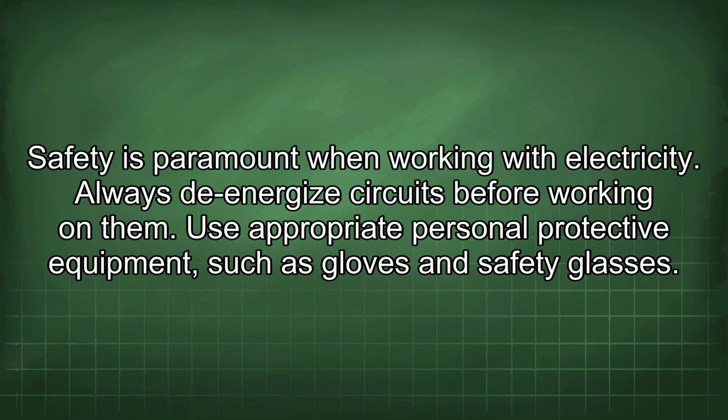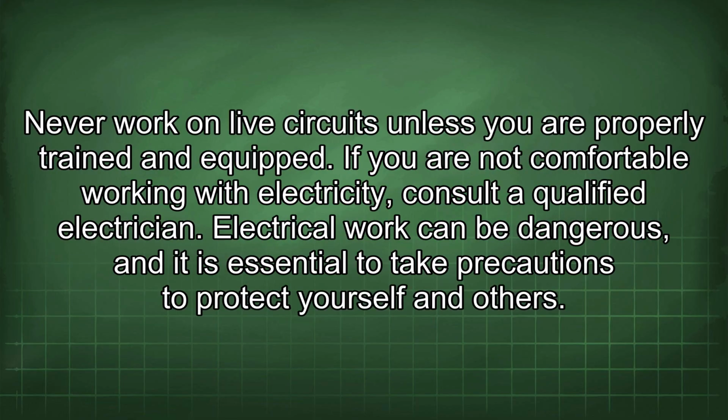Always de-energize circuits before working on them. Use appropriate personal protective equipment such as gloves and safety glasses. Never work on live circuits unless you are properly trained and equipped. If you are not comfortable working with electricity, consult a qualified electrician. Electrical work can be dangerous, and it is essential to take precautions to protect yourself and others.